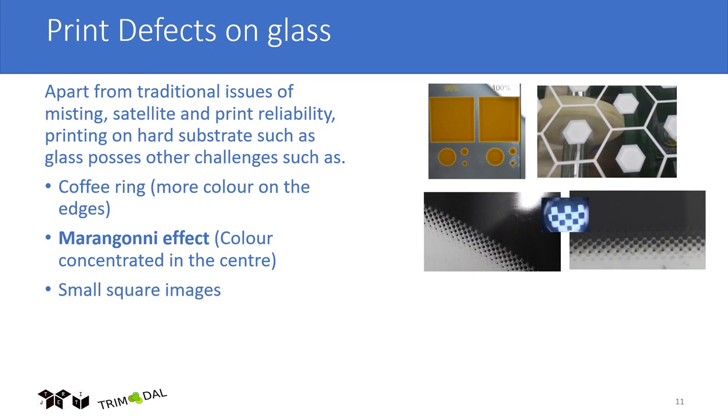Again, another problem. This is for the automotive replacement market. Look at this, the square definition. You see some cars in the front have a square, a circle. If they have a circle, it's quite easy. They love it, right? If you have a square, it's difficult. Sometimes by the time you coat it, it may convert into a circle, because the drops like to be circles. These are small, and if you look at the definition, it's very difficult to get a square. It's triangular. And you really have to tweak the viscoelastic property to get it right once it lands on it.